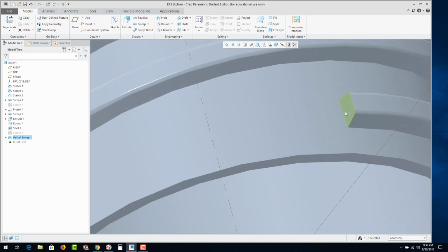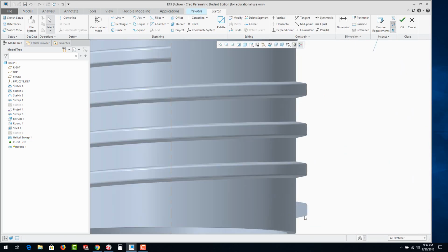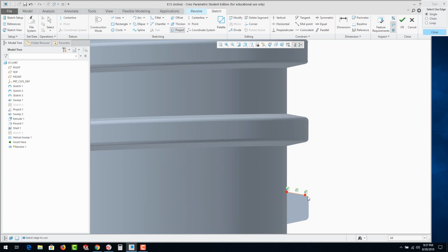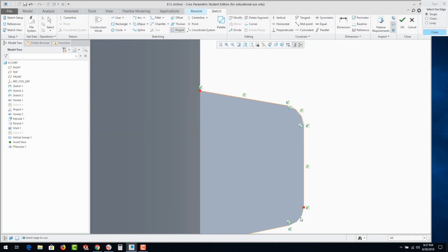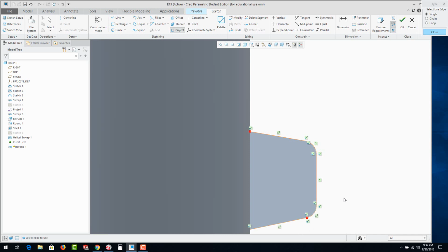So here's how to do a real lead-in. Select this face and go to Revolve. Zoom up to that face and proceed to project the edges on the outside. Make sure, I must have missed that edge. Might actually have more than I need. I'm going to wipe those out because I think I clicked twice on an edge and that's sloppy geometry. So make sure you don't click twice. You might end up with a fragment locked in there. Okay, I think I'm good.